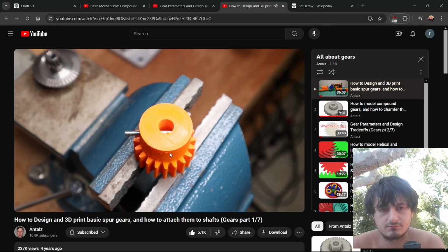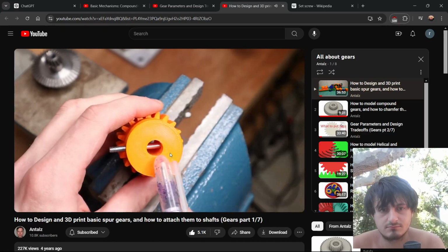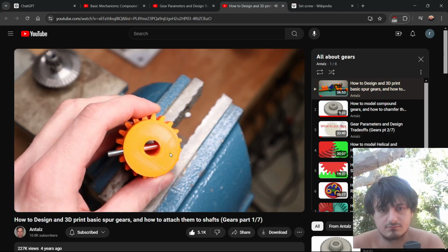You may have noticed over the past few shots that the screw of this gear is a little bit too long. But I would like to point out that the reason for this is because this screw has a piece of smooth shank, and it is this smooth shank that is in contact with the shaft, and this ensures a higher amount of strength and also provides a little bit less backlash.